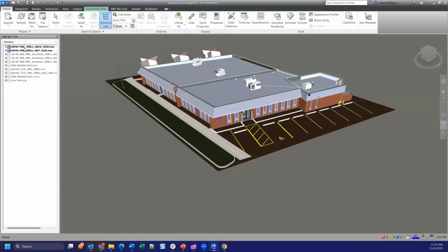Now, if we look at the point cloud data from a single scan point of view with the tripod-based scanning, what you're going to see is an incredibly dense measured point cloud that almost looks like a photograph. But when we register those individual scans together to build our project point cloud, and then we want to pull that project point cloud into CAD, that data needs to be downsampled. So it's not going to be as dense, not as thick as what we were looking at in the web viewer.